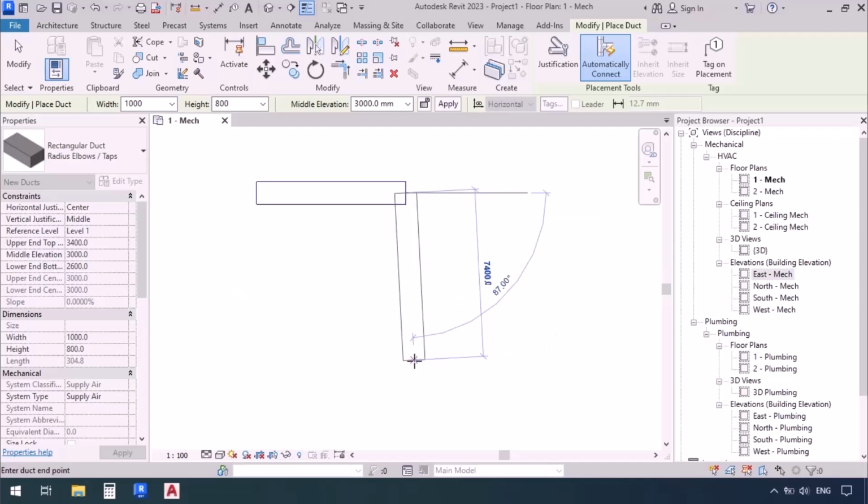For the continuation of the duct, we can determine the facing of the ducts by moving our pointer, as in we can give it an angle, and this angle could be from 0 to 90 degrees. And as for the length, we can either guess it using our eyes, or we could just enter the number that we want from our keyboard.